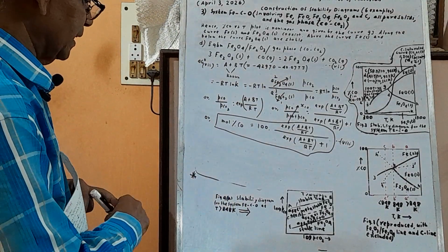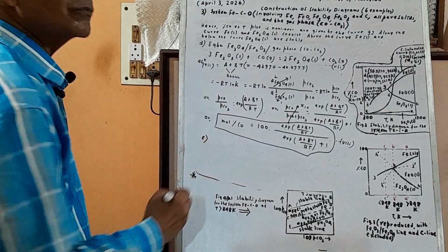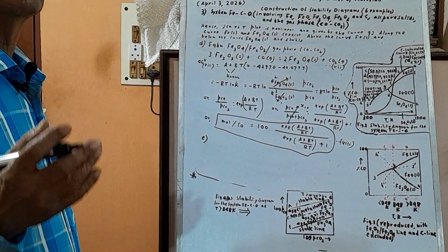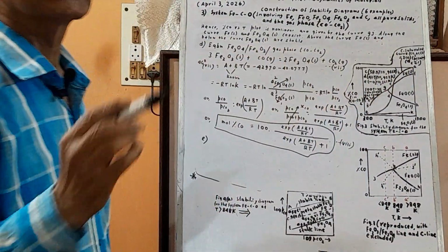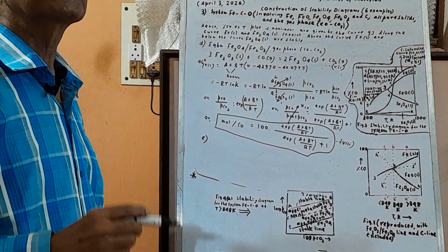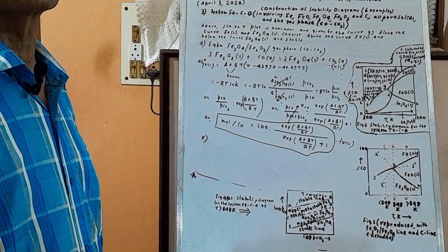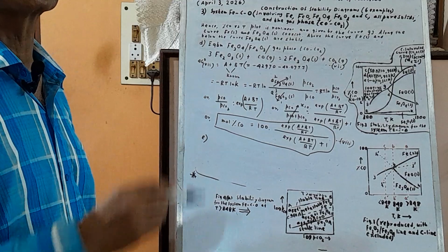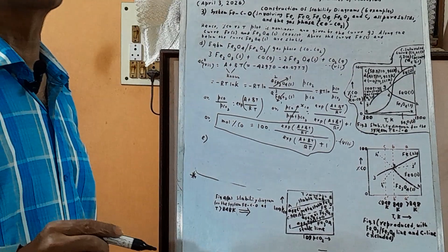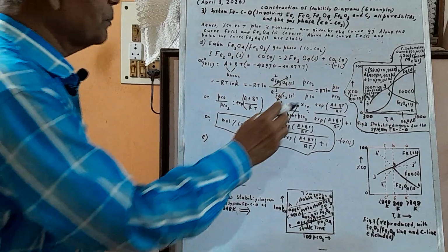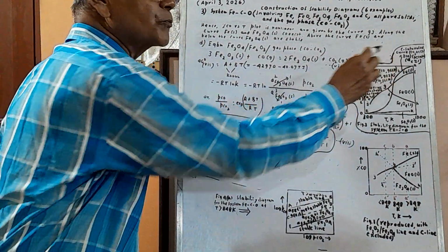This is the E. Carbon curve means this reaction: CO2 plus C is 2CO. Equilibrium under activity of carbon 1, which we call carbon saturation. And this is a pressure specific reaction.